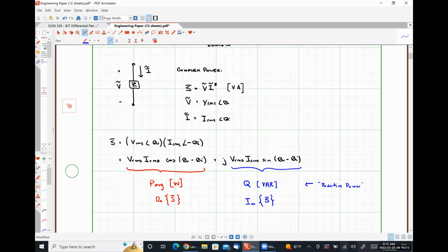So consider a classic example of what happened in Great Britain several years back, after, I believe, a World Cup match. Everybody turned on their electric tea kettles at the same time after the match was over, and it actually caused a brownout throughout London. It was because they didn't have sufficient reactive power stores to ride out that large increase in demand at that instant, okay?